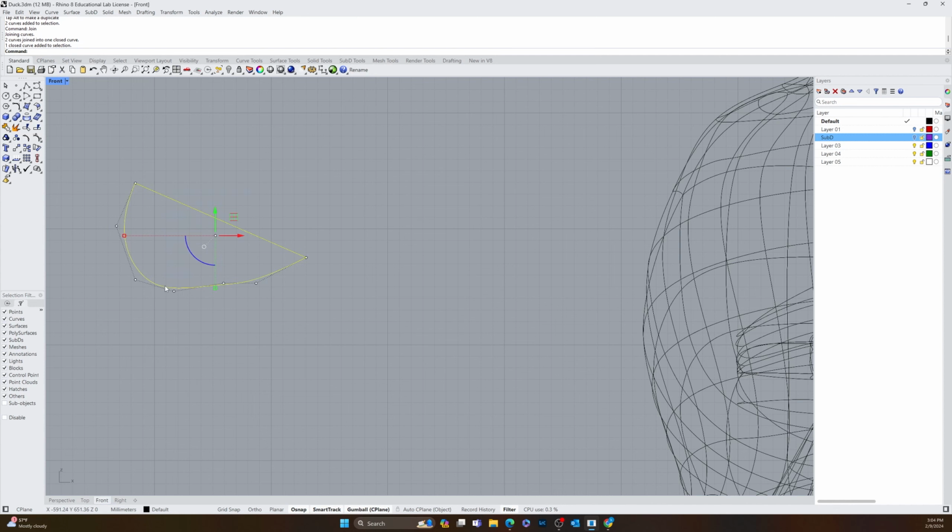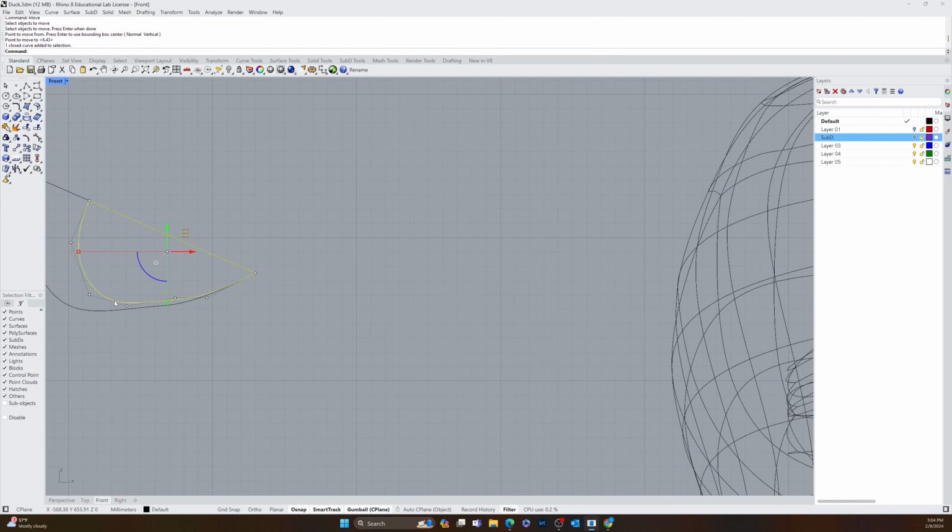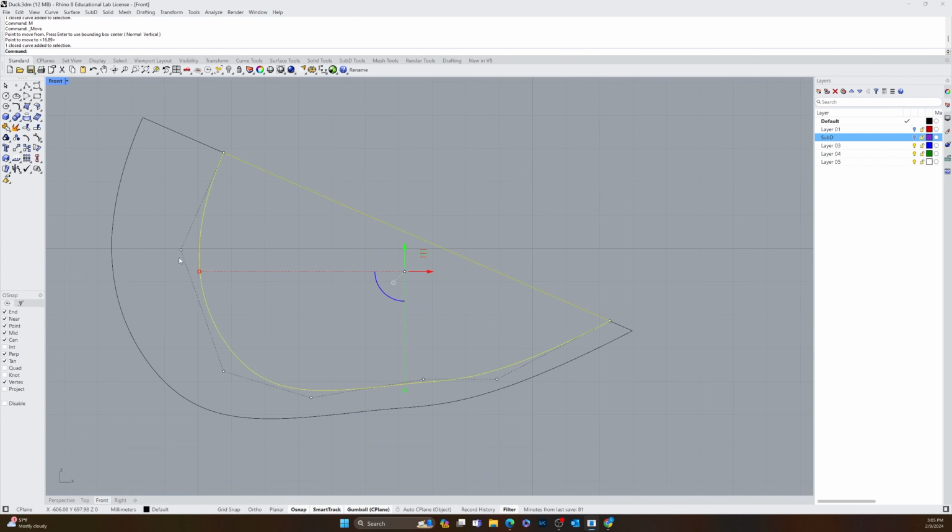And then I'm going to hit Alt, Shift, and click on this to make a duplicate of it. Then I'm going to move it from here, like maybe down to there, and push it back just a little bit along this line here. So move again from this point. Now I'm going to make sure that on my selection tool I've got my near turned on, because then it'll snap to this no matter where I put it, so I can make sure it's right on that line. Great.